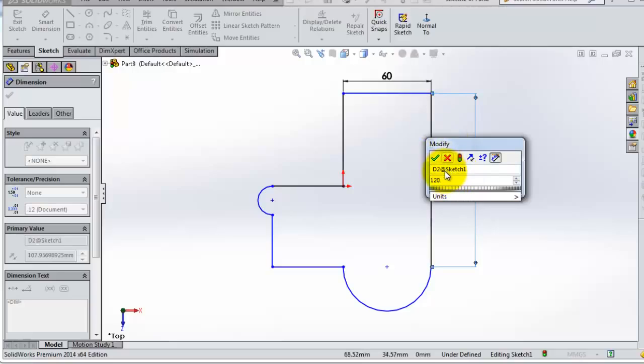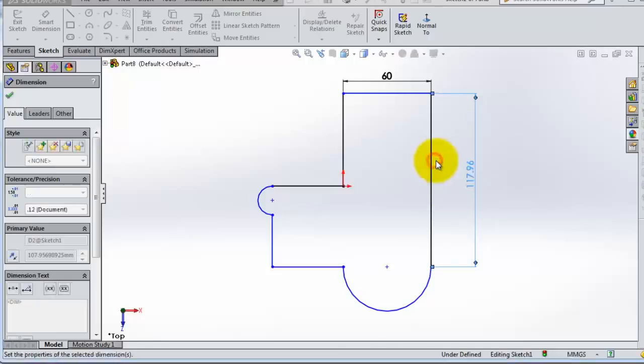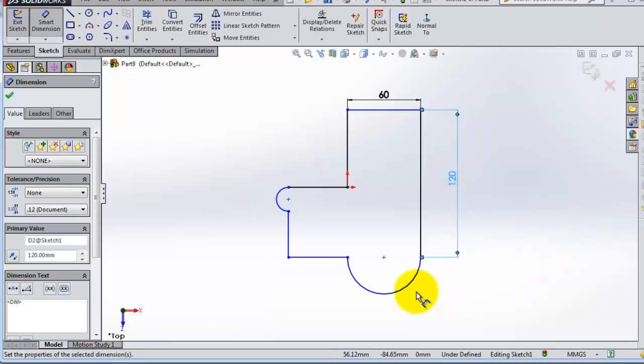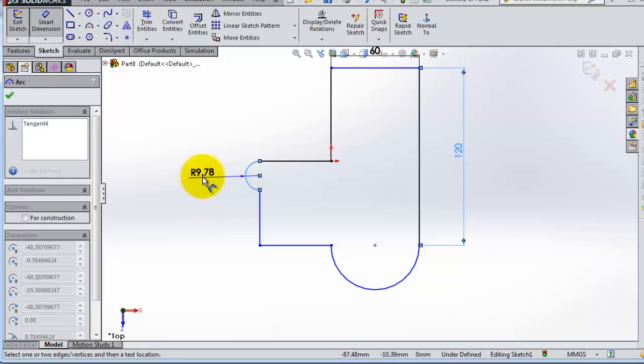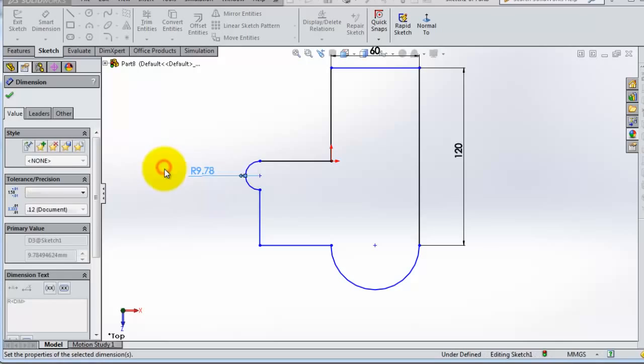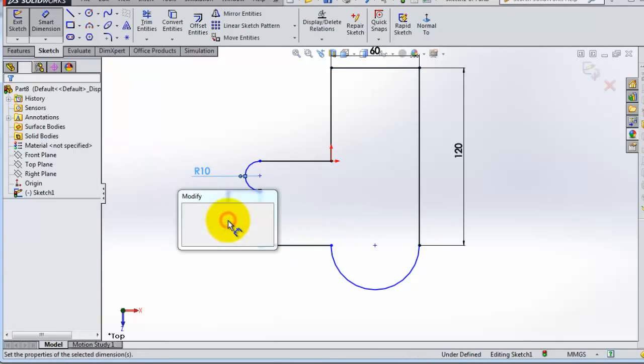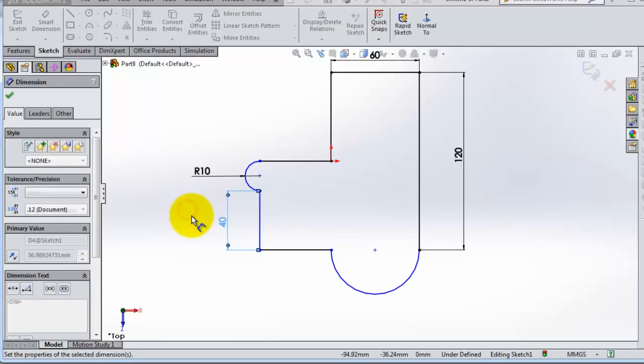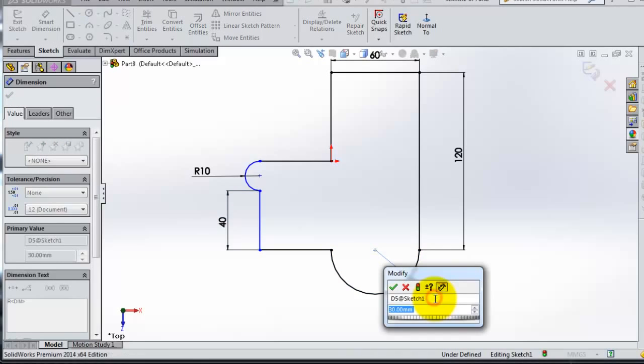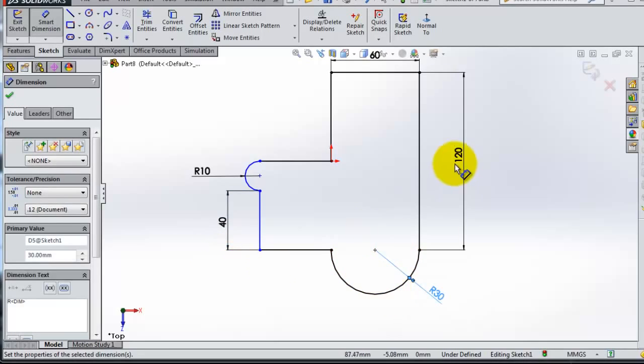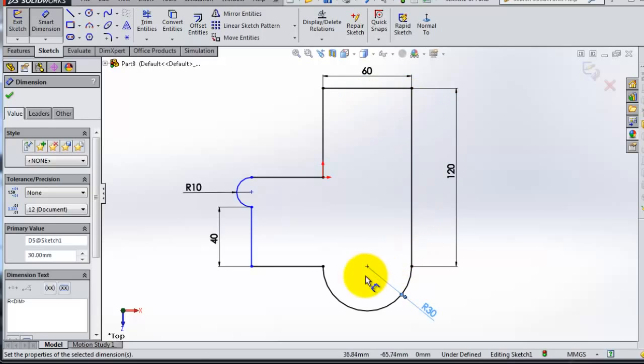In the advanced tutorials, you'll be able to make the dimension parametric or controlled by some equation and so on. But for now, let's just select the dimension to be 120, click on it, then OK. We are able now to continue adding more dimensions until we define our part. So you notice now the lines are changed.